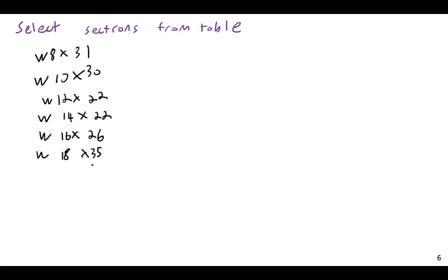But if you're designing a building that's 30 floors high and the number of floors you can sell is directly related to the height of each floor, then you're actually really worried about the height of the beam. If you think about a building, when we draw them as frames in structural analysis, we usually draw them as line elements, but in reality it's not like that. Between each floor, there is usable space. There is the floor.